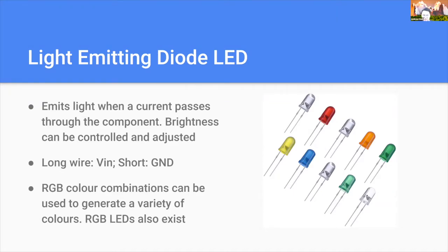And the long pin is for voltage in. And remember how we talked about common ground? You have to always have this ground connected to the ground of the board, Arduino Uno. So the short pin is the ground, and make sure you connect that. Whether directly, you can solder a wire into it, or you can put it in an expansion board.